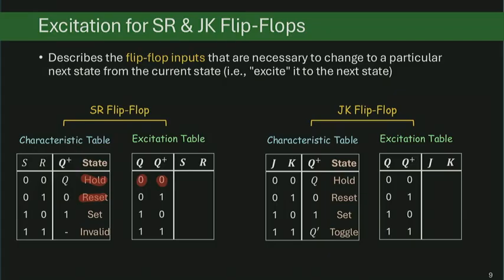What do you mean by you have a choice? Well, as long as you put the S input to be a 0, then you can realize the transition. You don't have to worry too much about the R input. If S is 0, that allows me to move from 0 in the current state to 0 in the next state. And that can be very compactly described as 0x.